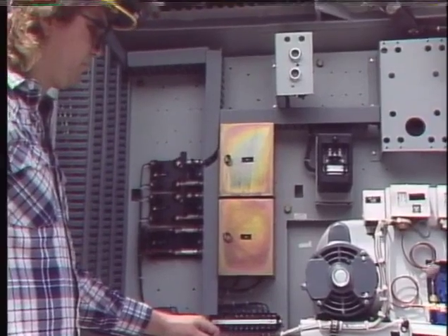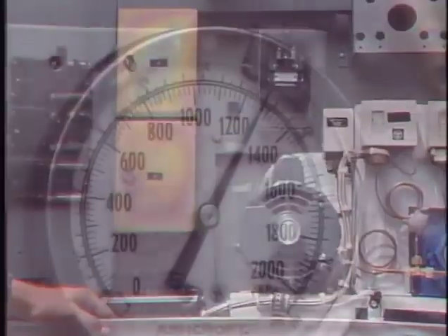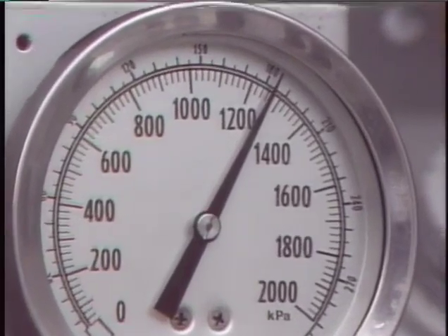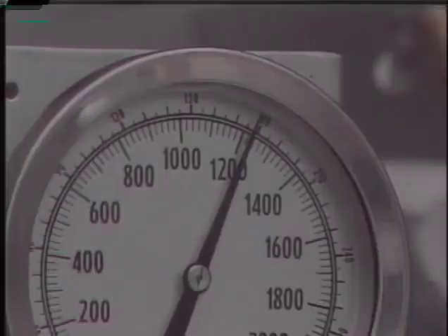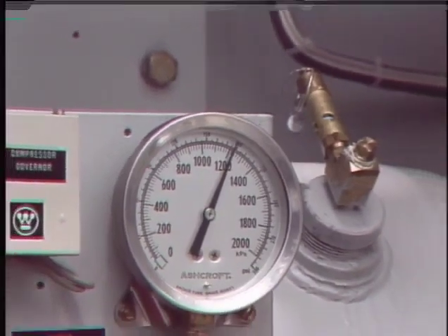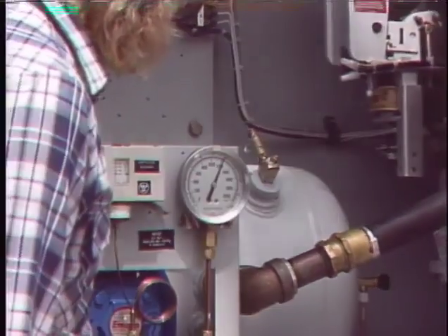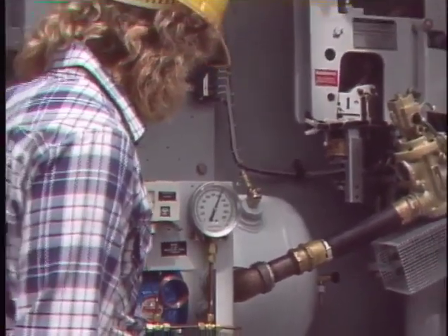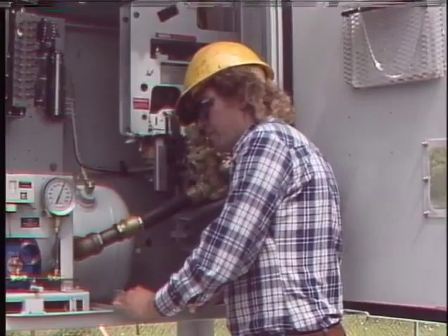When system pressure has stabilized, the air supply system can be checked for leaks. To determine if the system is leaking, take the system pressure reading. Wait a period of time specified by the manufacturer, and then check the pressure again. Any difference in the readings for the given time period can be converted to a rate of pressure drop. If the rate of pressure drop exceeds an allowed tolerance, there may be leaks in the air system.